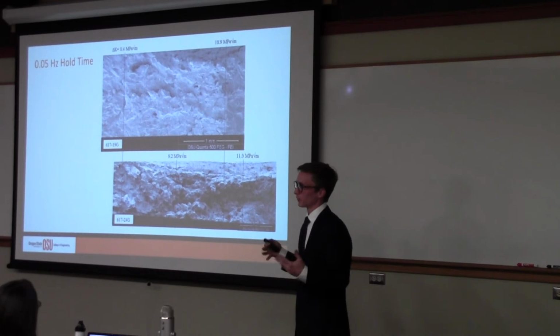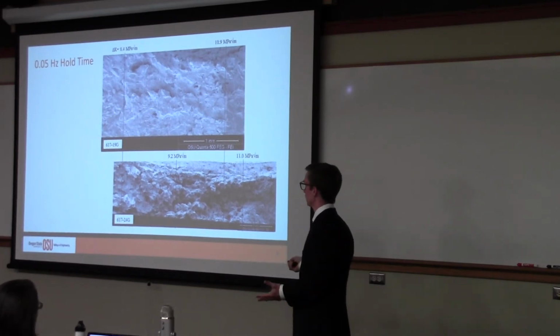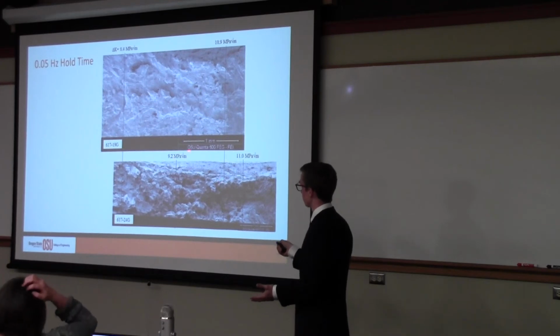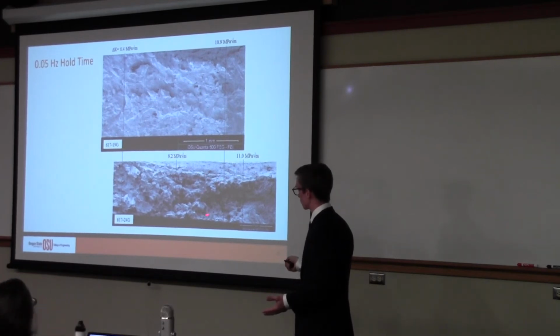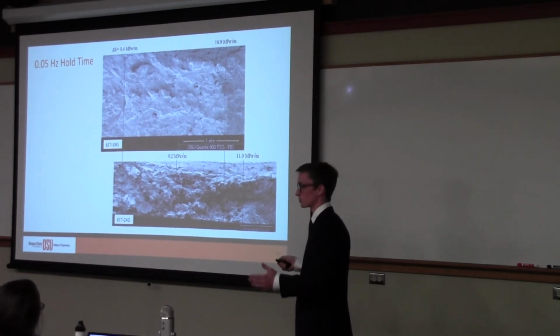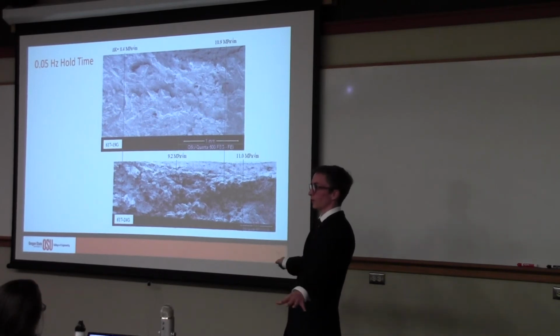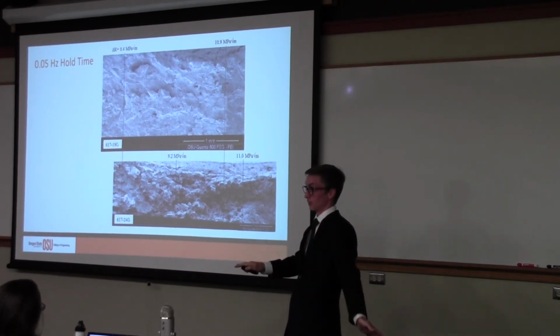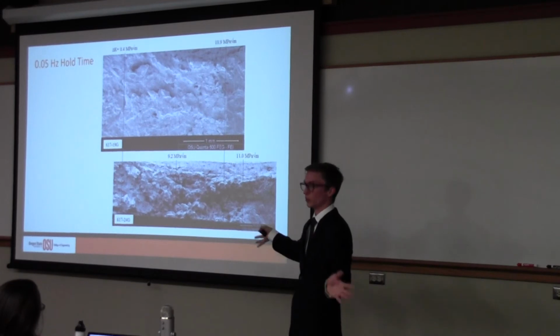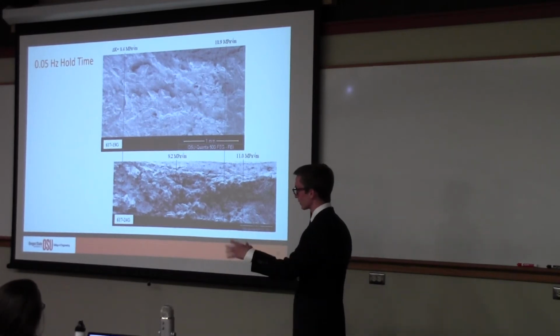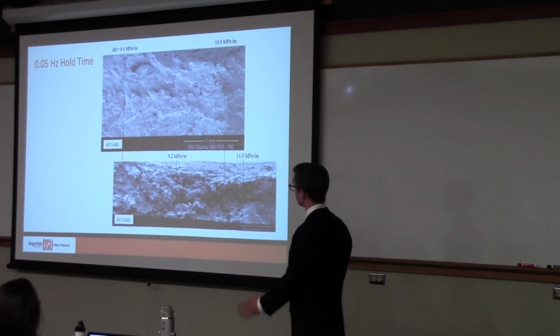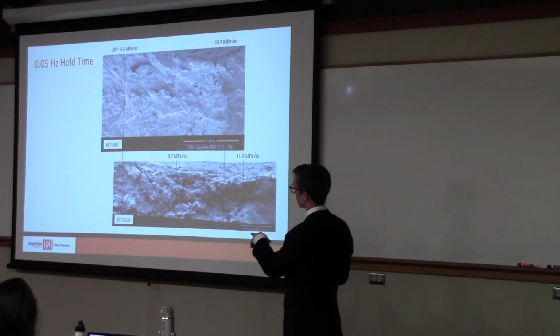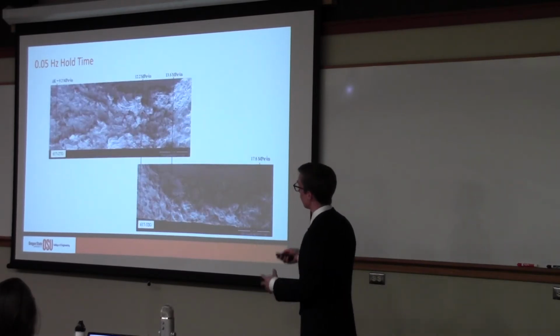So it tripped this other mechanism, but the takeaway is that even though this is kind of below our threshold where it breaks away, we saw this different fracture surface, but we don't see higher crack growth rates than the green dots or even the blue or the purple ones. So we'll look at the graphs again and try to reiterate that point, but if we look at 2 other hold time samples, we get a better idea of the transition.